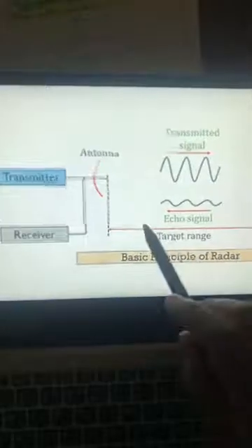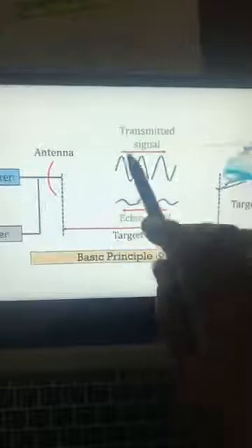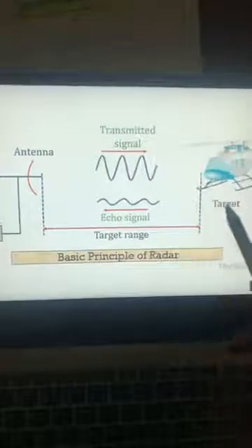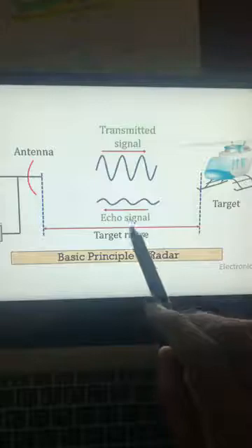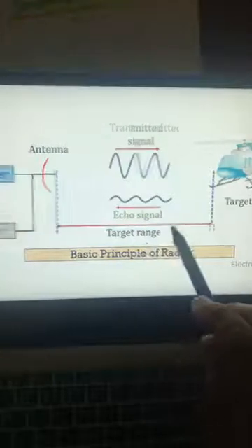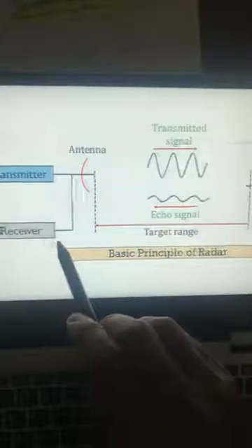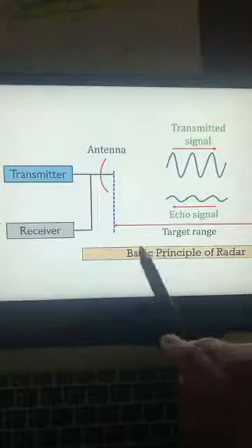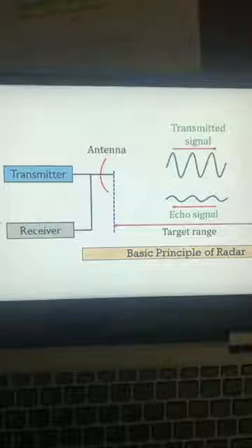Another way to look at it: this is the transmitted signal, it hits the target, and a very weak signal which has an echo in it, with a Doppler frequency in it, comes back and you receive it in the receiver part. And the radar, as I mentioned earlier, is all the time doing FFT. So you are actually calculating FFTs. So this is a typical radar receiver.